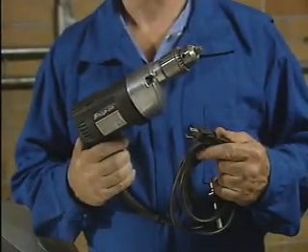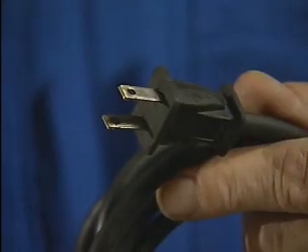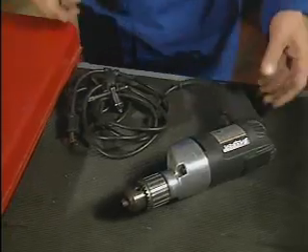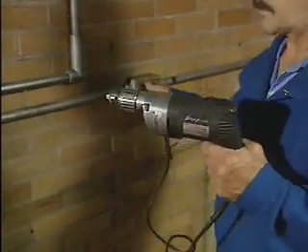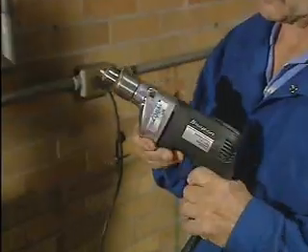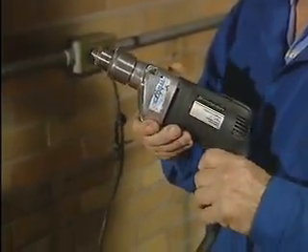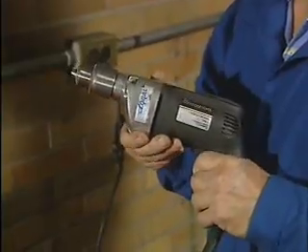If an electrical tool is double insulated, it does not have to have a ground conductor in its power cord. Double insulated tools have plastic casings that insulate the user from any fault inside the tool. If the casing is in good condition, there is little danger of shock. One word of caution is advisable, though.